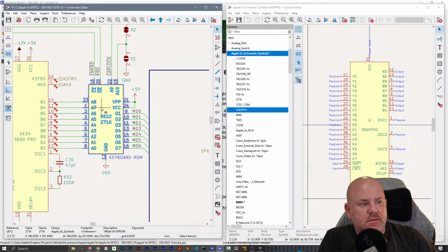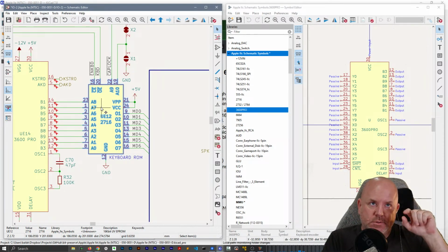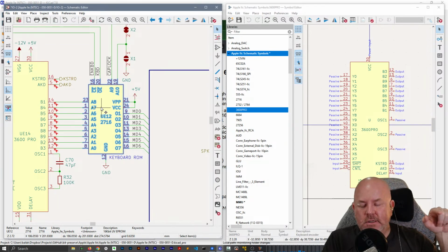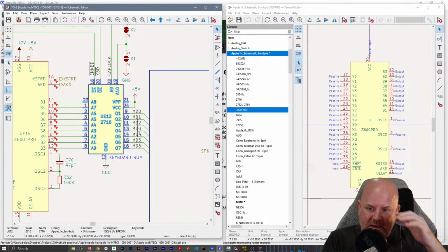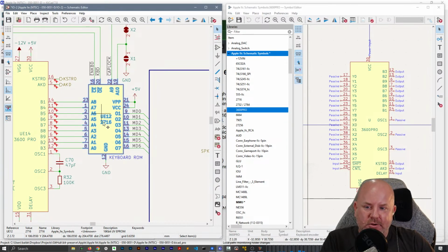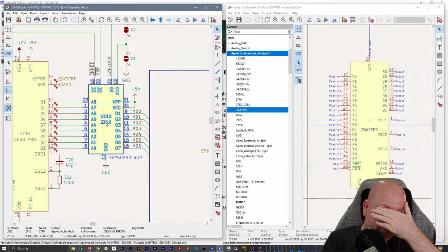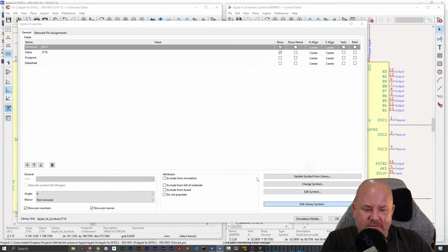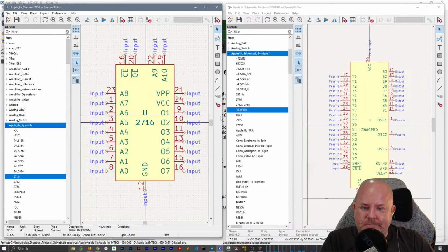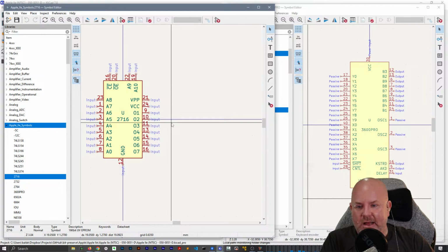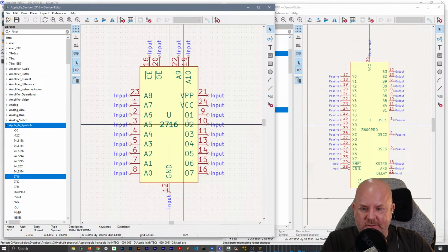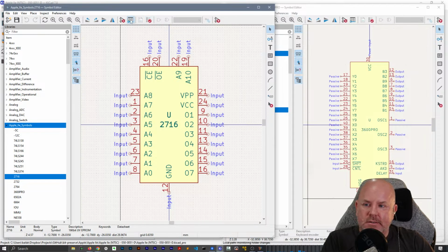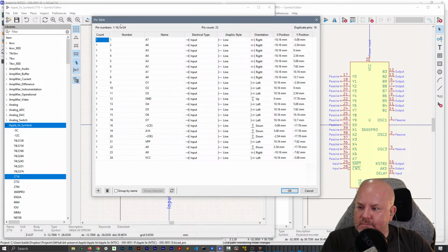And then when you hit the soft switch C000 or C010, that soft switch will enable the ROM to output an ASCII code onto the data bus. This is how you could map different keyboards to different characters, because you would replace this ROM. I think it's pretty cool. It's not at all how I would have thought the keyboard worked until I actually looked into it. It was not what I expected. I was like, holy cow.